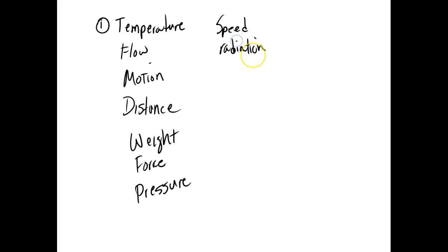I don't know if I'm going to sense that or not. We had sensors that sense that. We had what they call gauges where they check the gauge. So if they put a coating on anything, they want to make sure the gauge is perfect. What they do is they use an X-ray machine, and the X-ray machine actually measures the thickness of the coat that they put on there, which is pretty good. So yeah, they have those gauges.